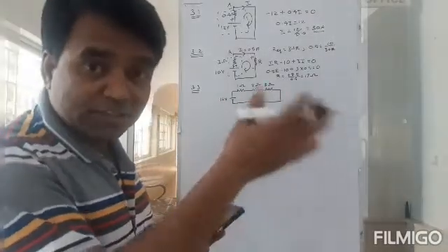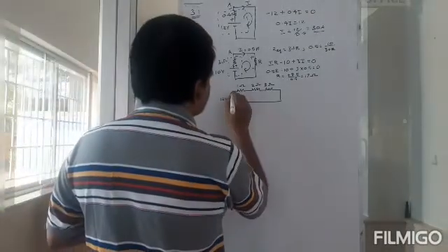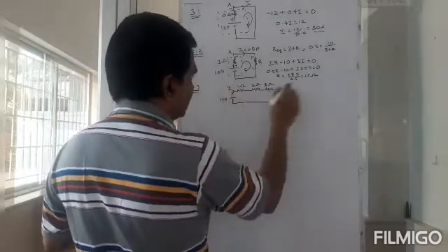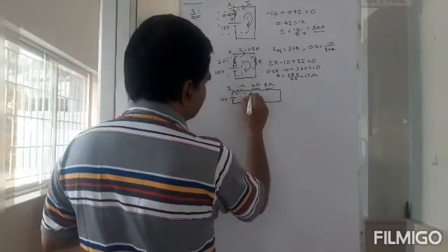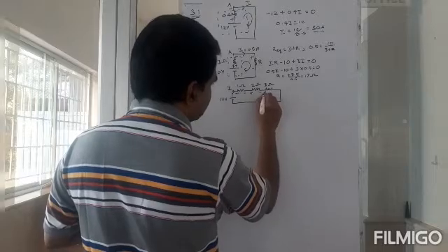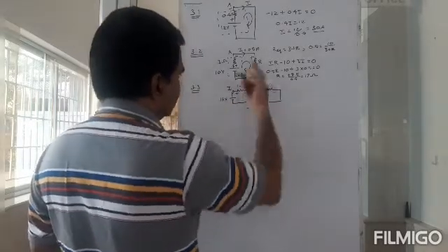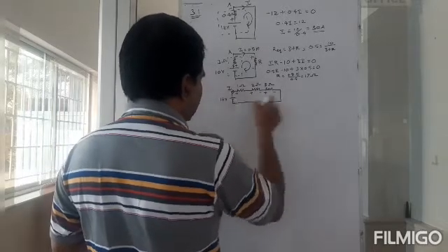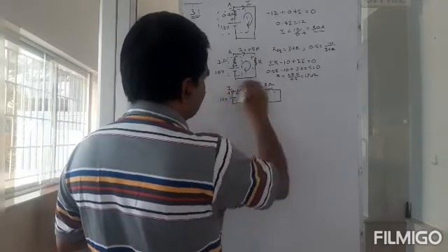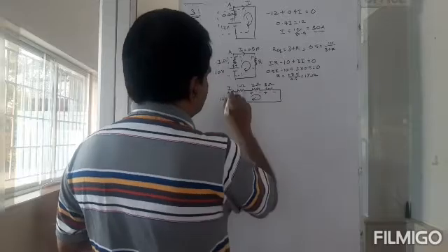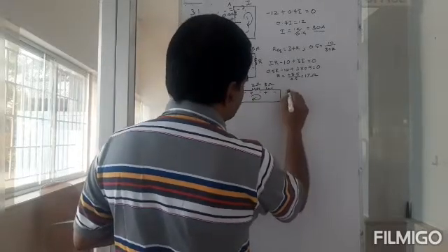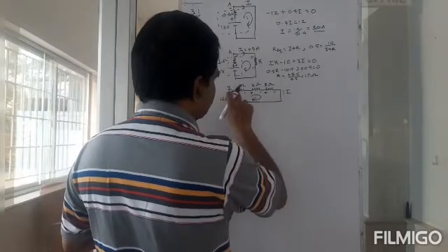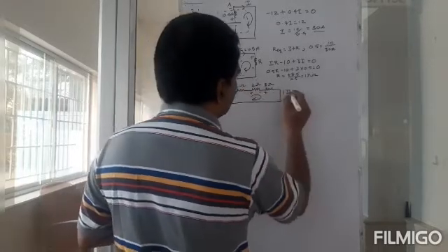But now I am going to use Kirchhoff's law. So I know that this is going to be some resistance, some current I. Because I am assuming the current to flow in this direction, plus, minus, this is plus, minus, because current is entering this way, then coming back. Okay. So then I will start from this point and I will come back to the same point. This is my A point. I will come back to that. So I into 1, right? So 1 into I. Then that is plus, because I am entering at the plus end. Then plus 2 into I.